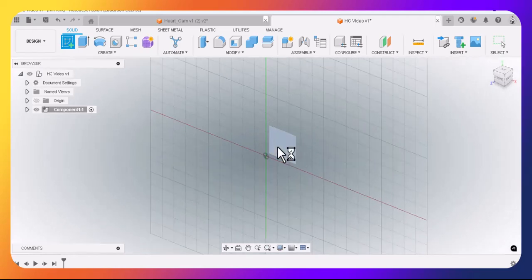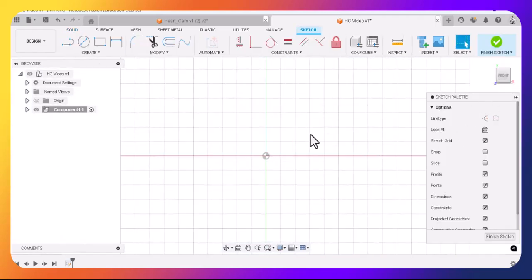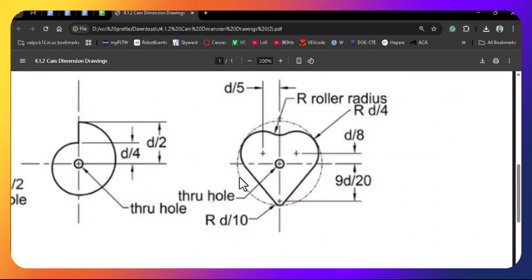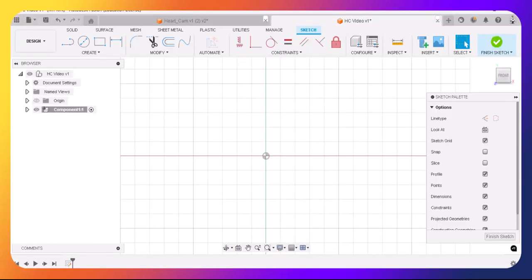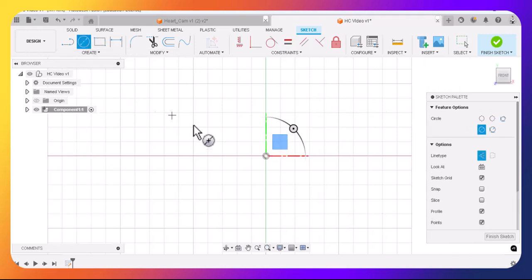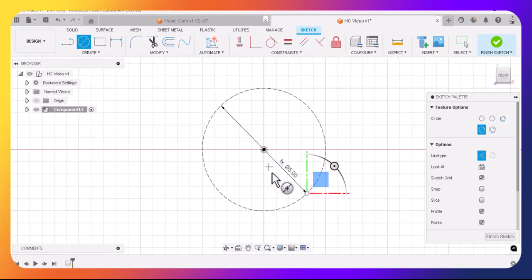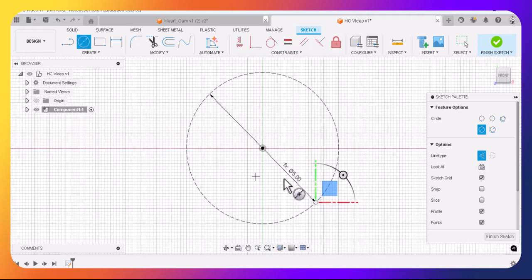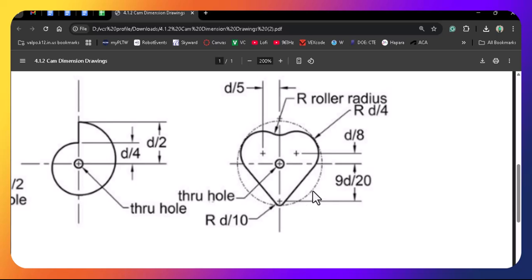Let's go ahead and create our one and only sketch on our front view. From here, what we're going to do first is create this outside diameter as a construction line. This outside diameter is going to represent the largest outside edge. So I'm going to come into construction, go to circle, come to the center, and I'm going to set this circle equal to my nominal diameter of 5 inches. And that there will become the overall outside border of our cam, much like we have here.